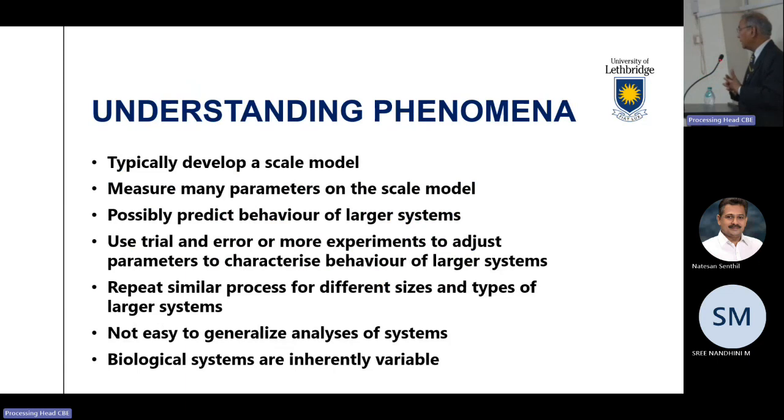And in early days, engineers used a factor of safety as high as 3. So whatever you calculate based on the model, you would multiply those values by 3 to make sure that the structure or system doesn't fail. With time, with improved understanding, the factor of safety nowadays is around 1.5. The impact of that understanding is significant because the material cost gets reduced in building the systems, and that has a large economic saving.